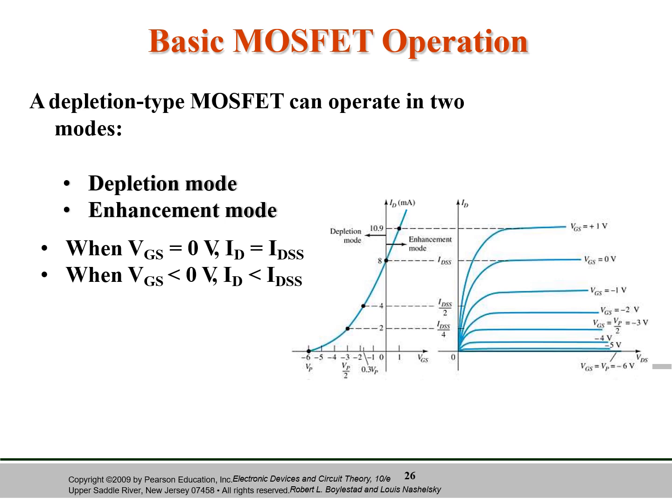Again, because of the pinch off region, current becomes constant here. But what happens when you make VGS negative? The negative potential at the gate will tend to repel electrons towards the positive p-type substrate and attract holes from the p-type substrate. But this results in recombination of holes and electrons, and there is a reduction in the number of free electrons. Therefore, the ID decreases with increase in negative gate source. So here, with negative gate source, the ID is reducing.